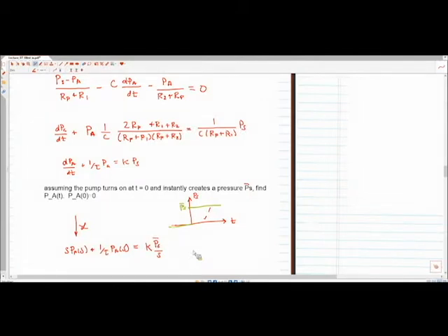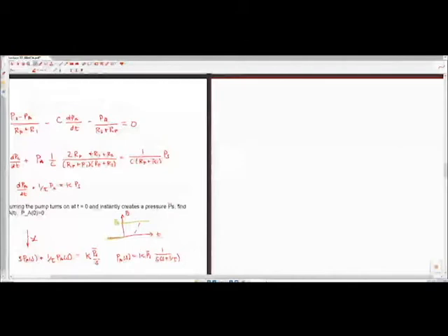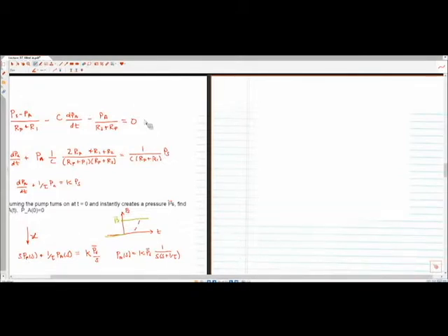So that means then that PA of s equals K PS bar times 1 over s, s plus 1 over tau. Okay, so this is a very common Laplace transform. If you look in any Laplace transform table, you will have this relationship that we have in the time domain: 1 minus e to the negative at. If you go forward Laplace transform or reverse Laplace transform, you jump between these two, and this is a over s plus a.